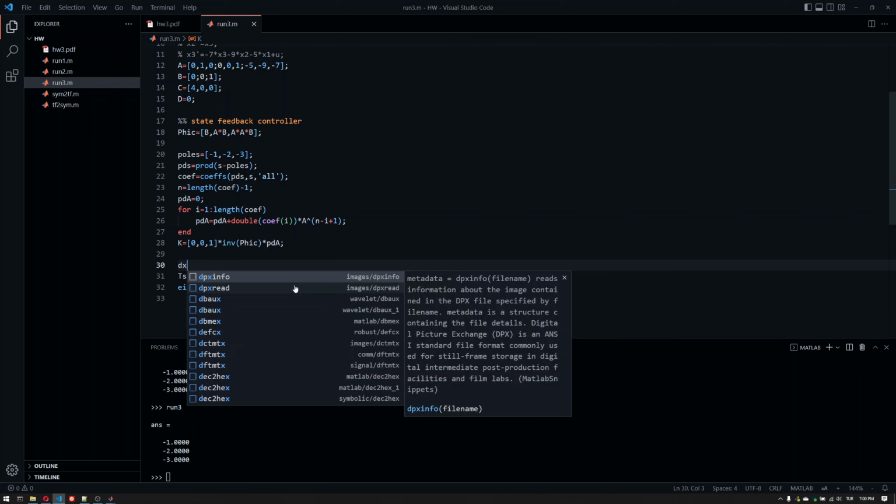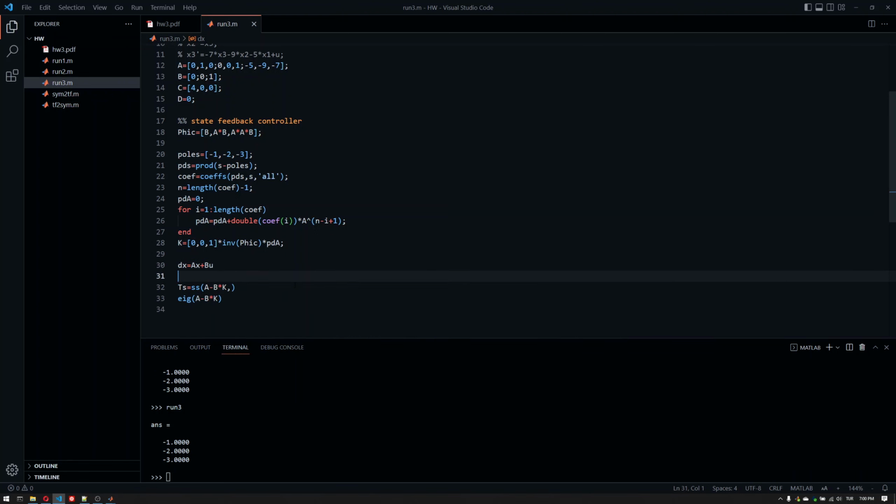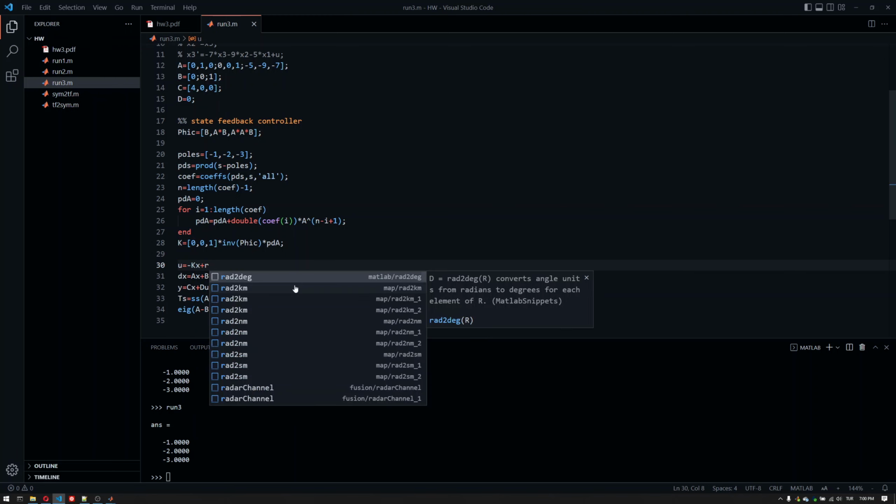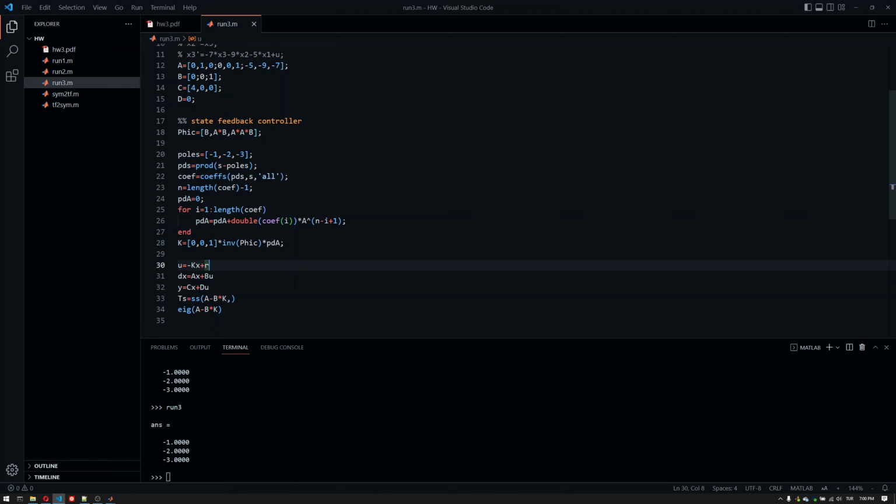Well, since we have dx equals Ax plus Bu and y equals Cx plus Du, if we plug in u equals minus Kx plus r for reference, what happens is that we get this here, and this would end up being minus BKx, and so yeah, minus BKx plus Br, and if we plug it in here, minus DKx plus Dr would be then the result here.